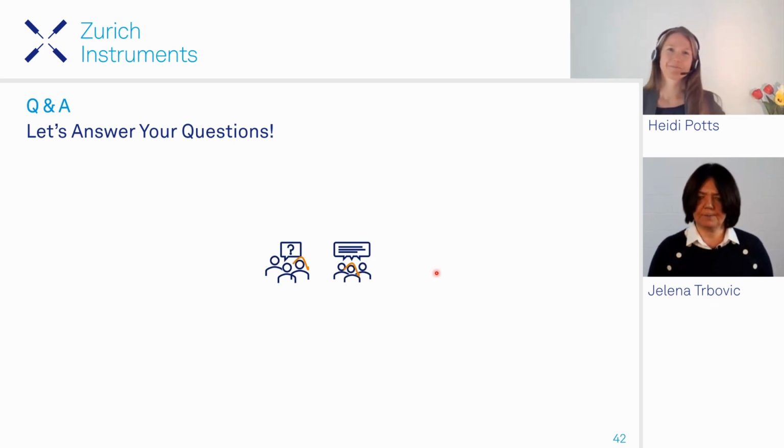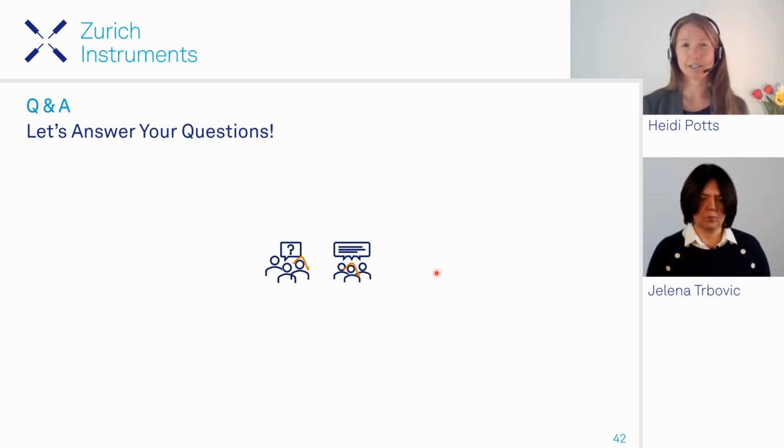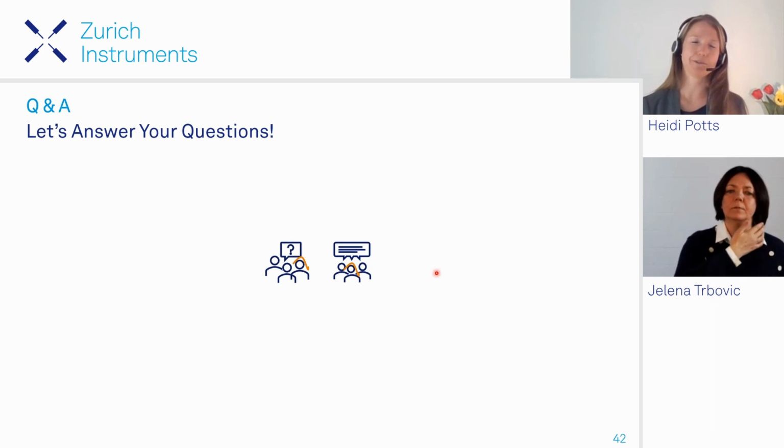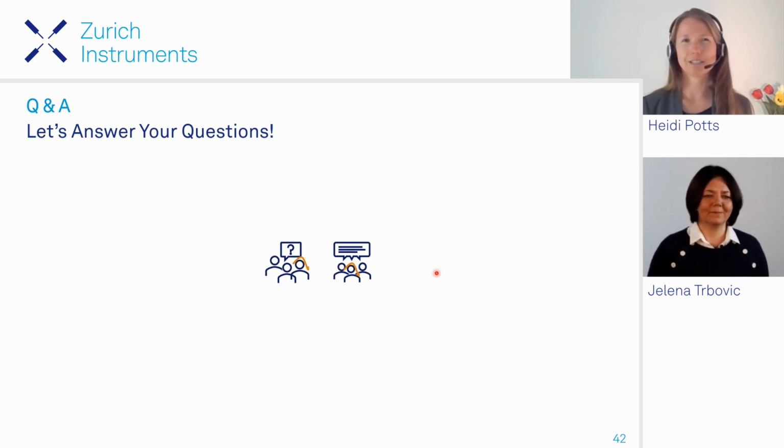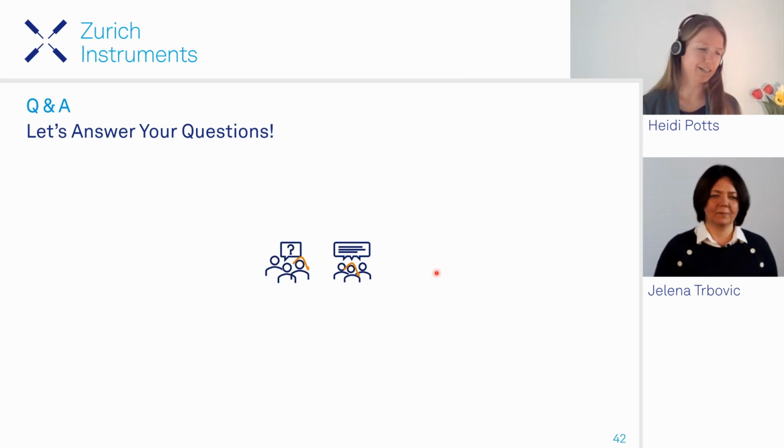What can you achieve? Yeah, that's a good question. There's basically two limitations. First you have to think about your measurement instrument, but then also about the rest of your setup. For your measurement instrument, in case of the UHFLI, the smallest time constant is 30 nanoseconds. So that means you could, in principle, get a data point in like 100 nanoseconds. But typically there are bigger limitations from other components in your setup. So more realistically, you would look at like a microsecond or so for a data point.